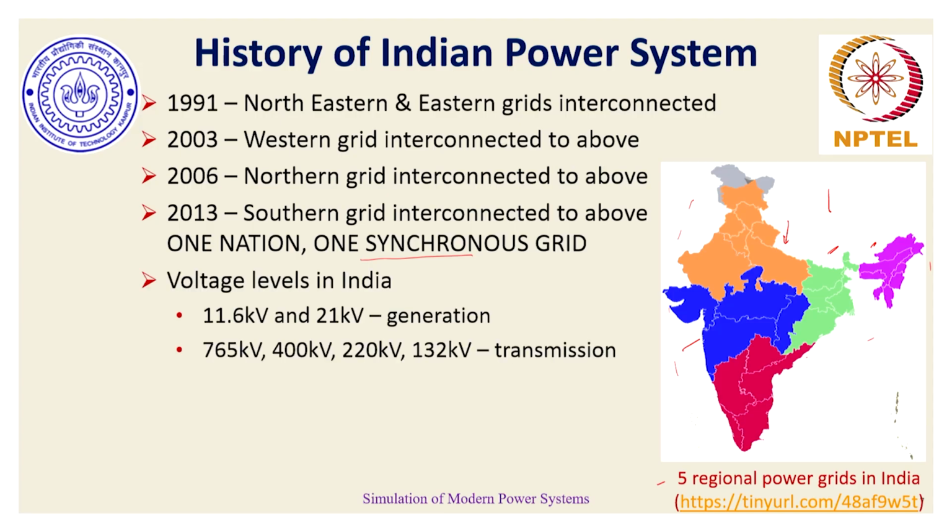Typical voltage levels in India vary from a few tens of volts to a few hundreds of kilovolts. Our generation typically happens at a few tens of kVs. Transmission of power at such low voltages would not reach large lengths, and if it were transmitted, the corresponding losses would be very high. That's where we have the transmission system, where the same power, transmitted at a higher voltage level, travels a larger length with lower losses.